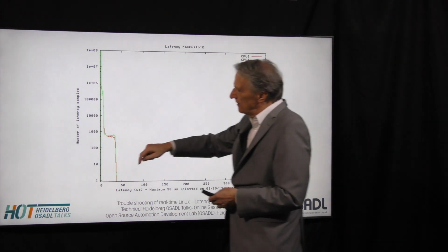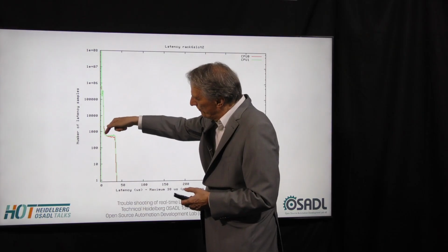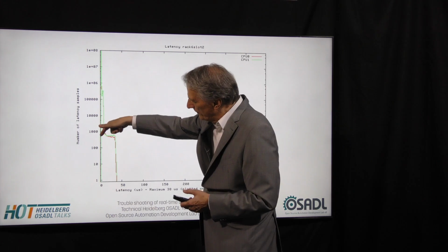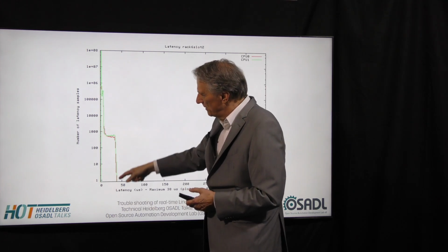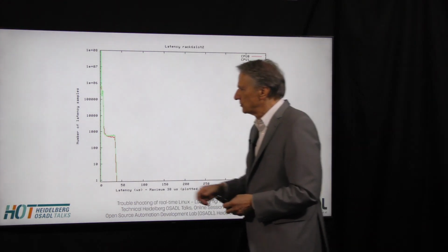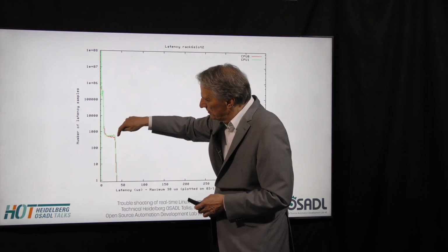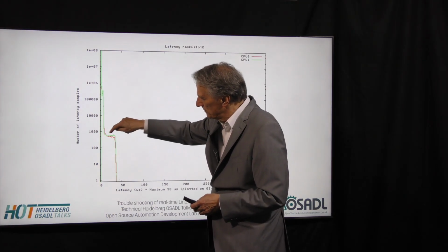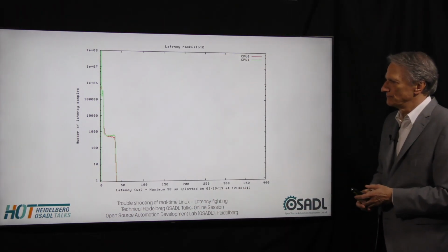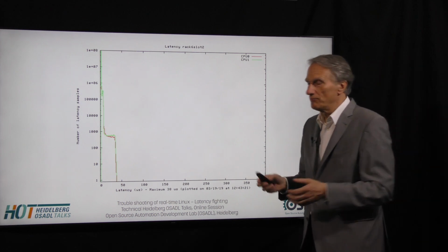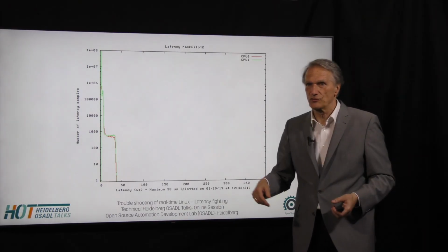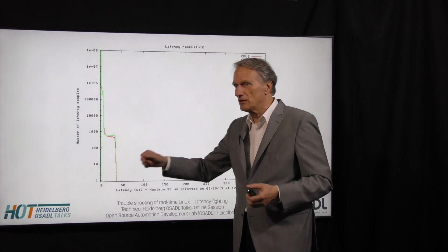But then we see a little curve, a plateau here in the range of maybe 700 to 800 samples in the amount of 40 microseconds. So something in the system is causing repeated latency values of up to 40 microseconds. Well, it may not be a problem, because your industrial control system requires something around 500 microseconds, and on this, 38 is still good.